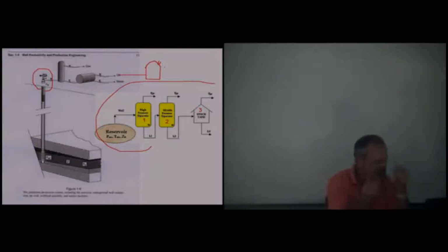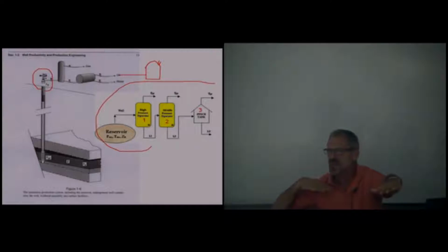So you basically try to separate the gas in a vertical separator because gravity is on your side. And then when you go to the second separator with just the liquid, you want surface area. You want as much surface area as possible to separate water from oil.